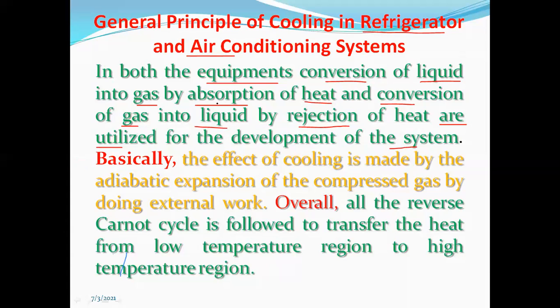In both the equipments, conversion of liquid into gas by absorption of heat and conversion of gas into liquid by rejection of heat are utilized for development of the system. So basically, the effect of cooling is made by the adiabatic expansion of the compressed gas by doing external work.